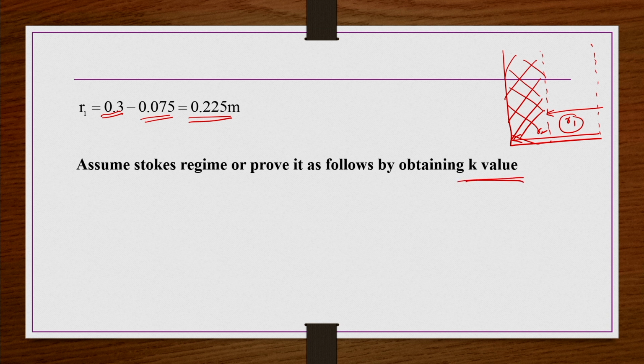Actually, whatever derivation that we have done till now, the working principles we developed, they are valid only for the Stokes flow regime. We have taken ut as r omega square dp square (rho p minus rho) by 18 mu, that is valid if the particles are settling under the Stokes regime. But whether the present flow conditions are within the Stokes regime or not, that we have to make sure. Then only can we use the corresponding QC equation that we derived.